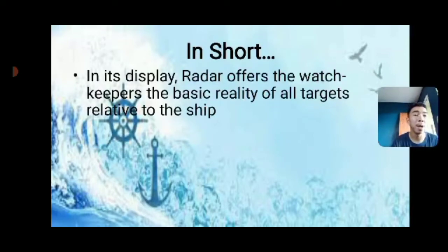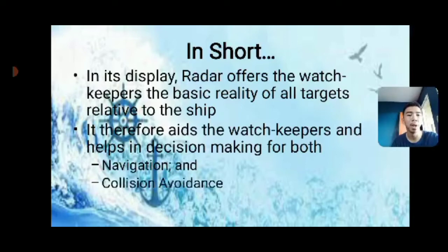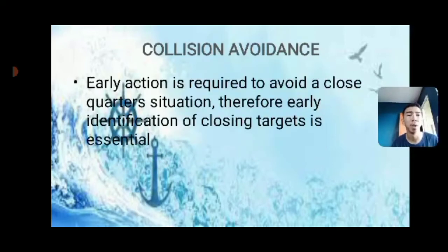in its display, radar offers the watchkeepers the basic reality of all targets relative to the ship. It therefore aids watchkeepers and helps in decision making for both navigation and collision avoidance. Collision avoidance: early action is required to avoid a close quarter situation. Therefore, early identification of closing targets is essential to avoid collision.